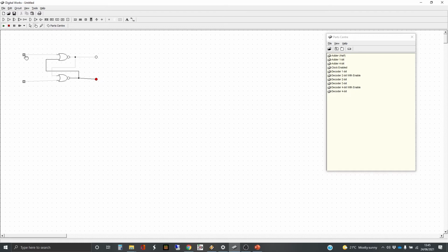And I'm just going to demonstrate that by flicking that on, and then turning it off. So we're back to where we were, in that the two inputs are both low, but the outputs have changed. And what it's doing is it's remembering stuff from earlier. And I was talking about the feedback loop. So now it's changed so that, because this output's low, this feedback's low, that's also low, so that makes that high. But then if you follow the full circle through, that feedback's high, it comes through to this NOR gate, and because that's high, the output from here is low.